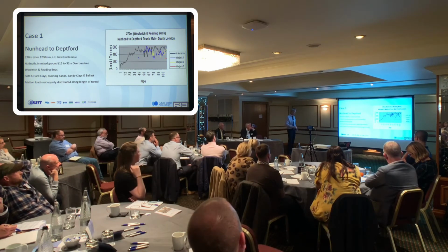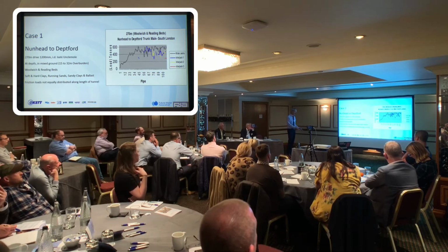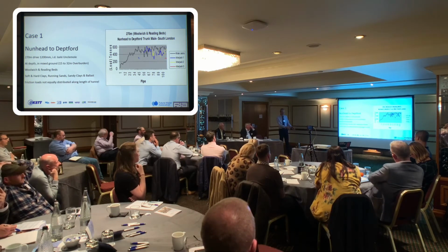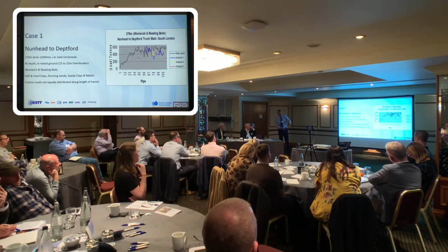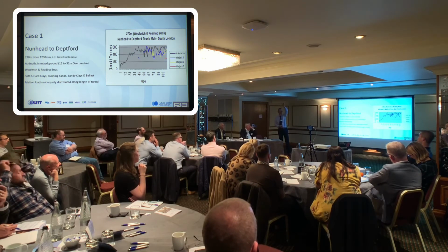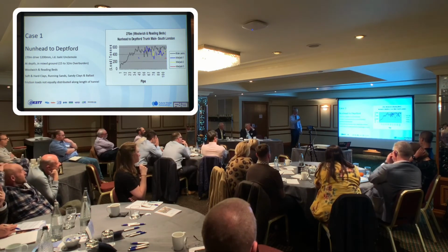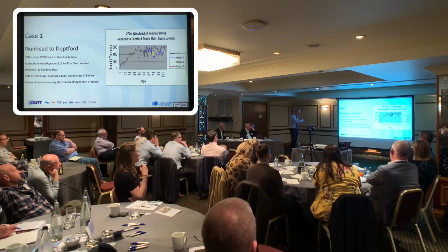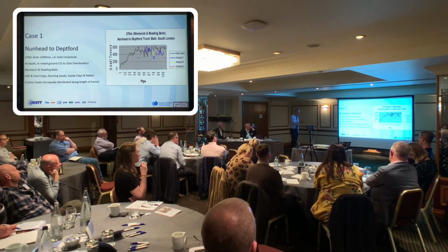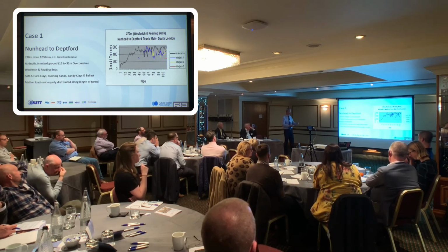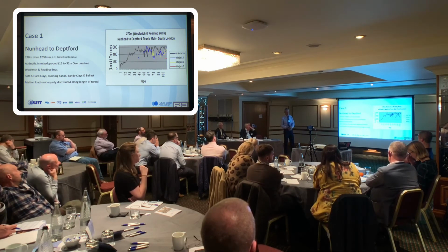We've also got an interesting ground profile where the drive starts at roughly 10 metres deep, goes under a road which is in cutting, then goes under a hill, and then it goes under a railway cutting, and then it's finally recovered at about 30 metres deep. So we've got different overburden loads in very different ground, and the way that the lubricant and the slurry operated was very important.